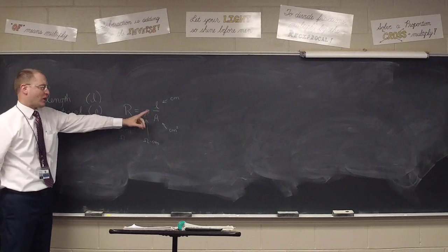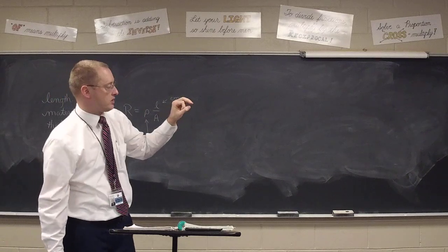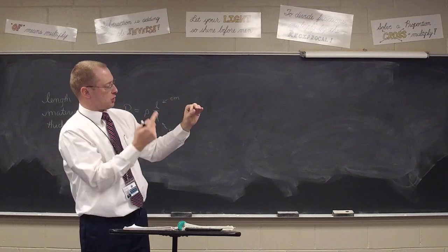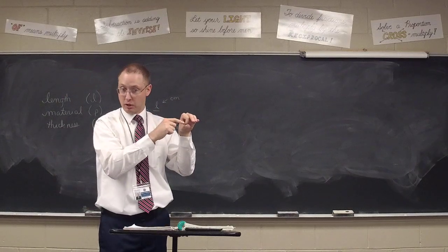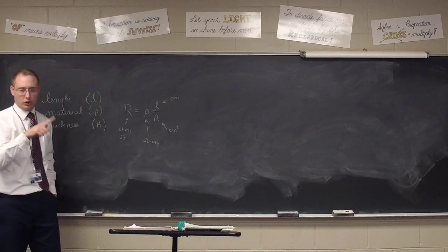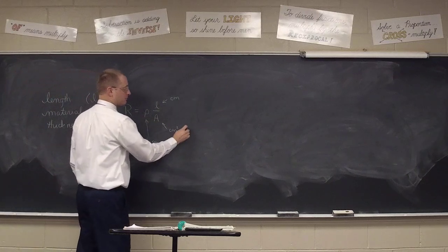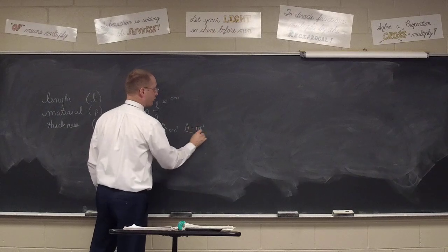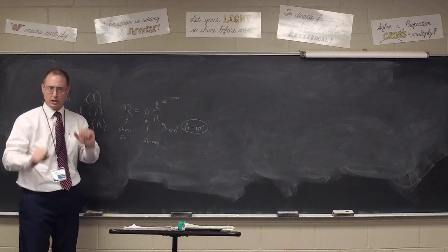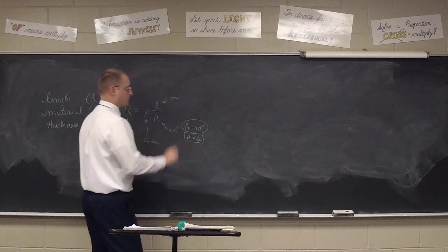That'll typically be given. Now, cross-sectional area. When I look at a piece of wiring, and there shouldn't be wiring quite this thick, I don't generally think, oh, that's the cross-sectional area. I usually think in terms of a diameter. Well, I've got to actually have cross-sectional area, though. How would I go from a circular cross-section, maybe a diameter or even a radius, to the actual area? Remember, the cross-sectional area would be pi r squared for a circular wire. What about ribbon wire, that rectangular cross-section? That's going to be simply length times width. Multiply the two dimensions times each other for that.